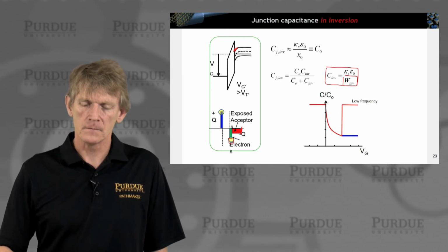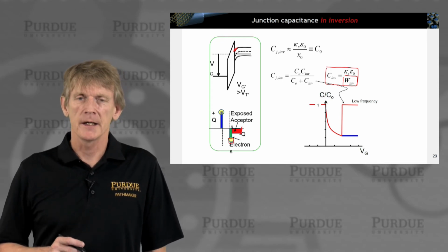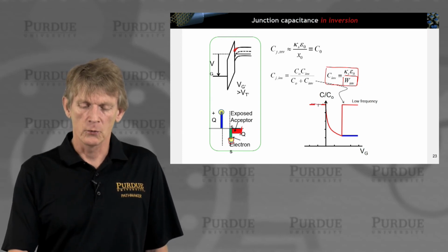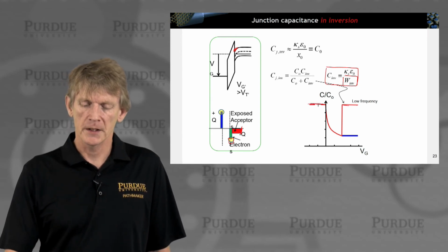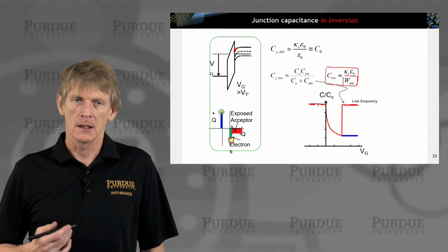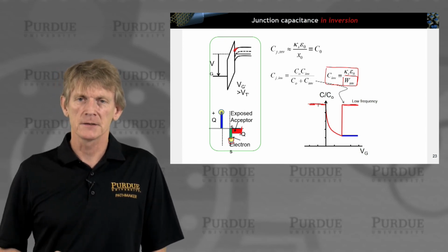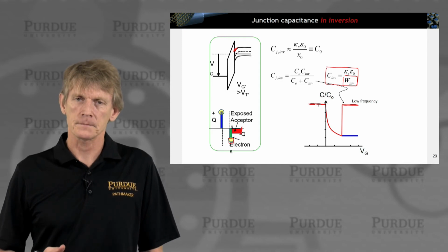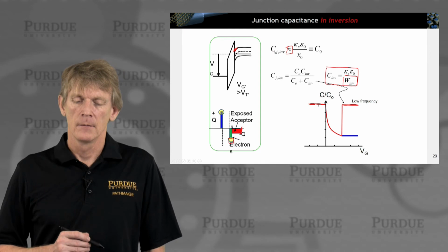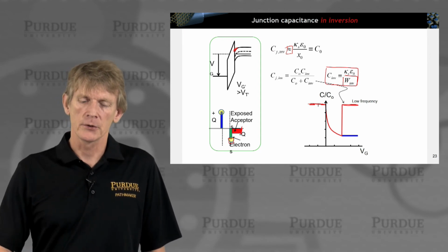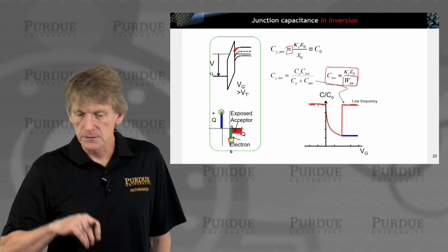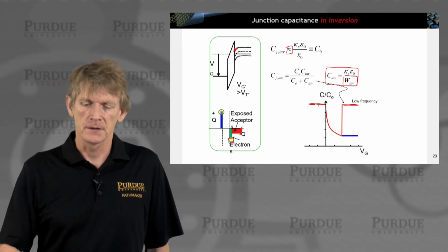Okay, so that is why in an ideal sense it jumps back up to ideally 1, where you take the capacitance to be just the oxide capacitance. Obviously, it is a series capacitance. It doesn't quite hit 1, but it's close to 1, right? But nevertheless, W inversion is finite, so the capacitance is there.